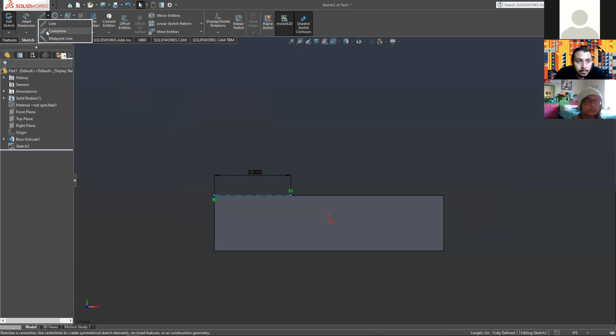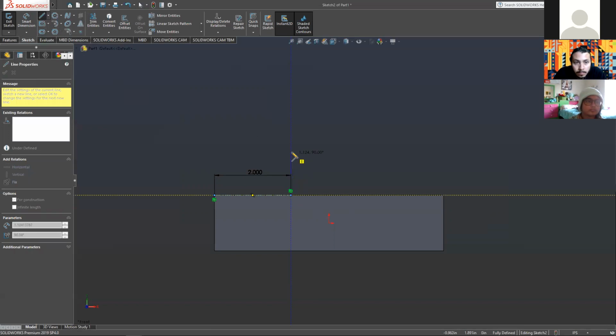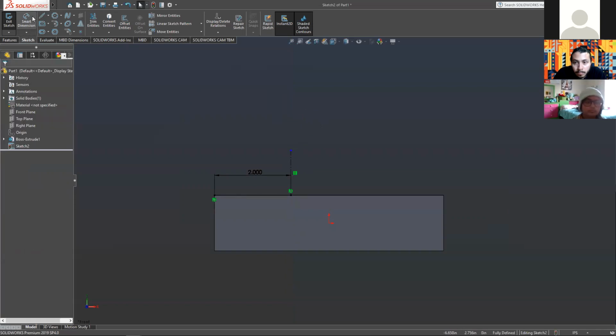But so let's get another center line, same way. Drop down key. We'll have it coming up 90 degrees perpendicular. SolidWorks will lock and set degrees like 45 and 90. As you can see, it pops out these yellow lines. So it helps you. You don't have to keep your hand steady to try and get that 90. It'll help you.